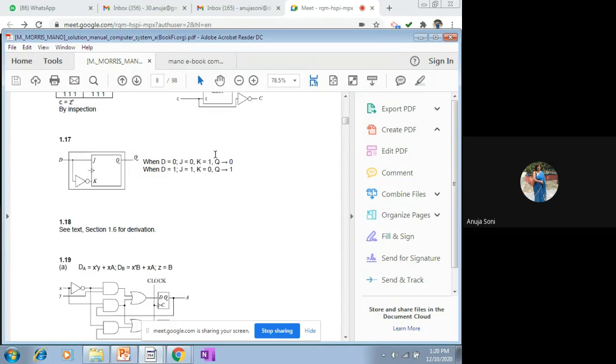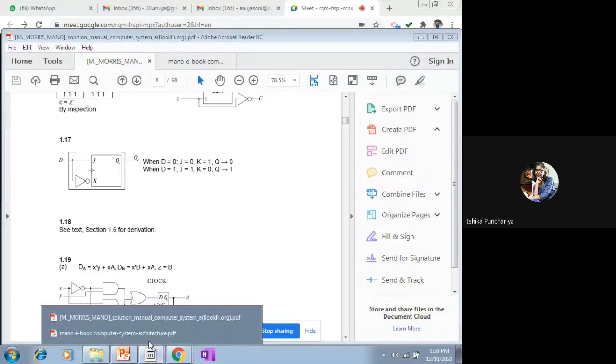D flip-flop. Now we can say that it is working as if the D flip-flop is working. So this way, JK flip-flop may be customized to work as D flip-flop provided one inverter gate is being used with JK flip-flop. Is that clear now? Similarly, you will practice making the D flip-flop yourselves. It may come in the exams. Now we come to the, yes ma'am, clear.